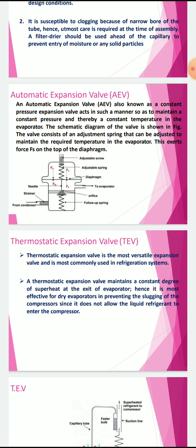When these two forces are balanced, then the diaphragm will not move. So the level of the flow rate of the refrigerant is fixed because of that adjusting screw.